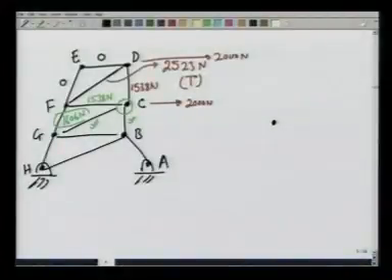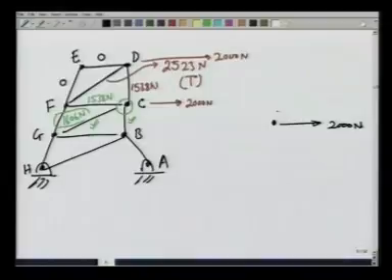So, let us balance the forces on point C. On point C, there is a load of 2000 newtons acting this way. FCF is a compressive force because it was pushing point F outwards. So, here also it pushes point C this way, 1538 newtons. Similarly, FCD, which is a force which was pushing point D up, is going to push this point C down with 1538 newtons.